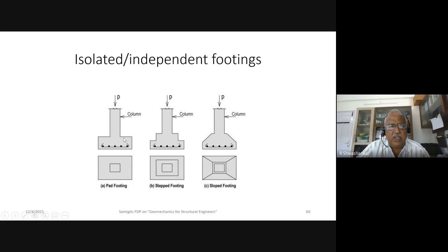Here again, when I say geotechnical design, there is not much confusion, because we take the load from the superstructure. I add 10% of the load from the superstructure as the weight of the footing. So my total weight transferred to the soil is this column load plus 10%. This I divide by the SBC. How you calculate the SBC is again a different matter. So I get the area of the footing. When you provide that footing area, two things are automatically taken care of: the contact pressures will not increase, and the settlements will be within permissible limits.